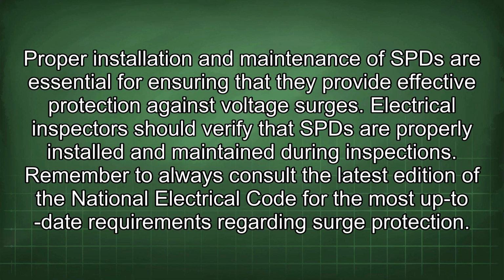Proper installation and maintenance of SPD are essential for ensuring that they provide effective protection against voltage surges. Electrical inspectors should verify that SPD are properly installed and maintained during inspections. Remember to always consult the latest edition of the National Electrical Code for the most up-to-date requirements regarding surge protection.